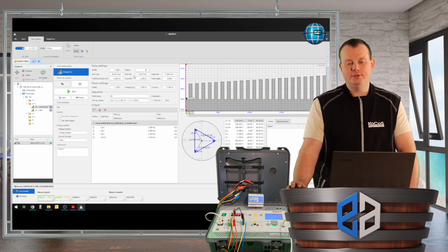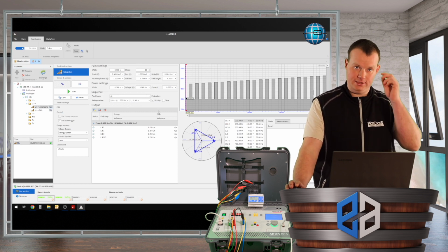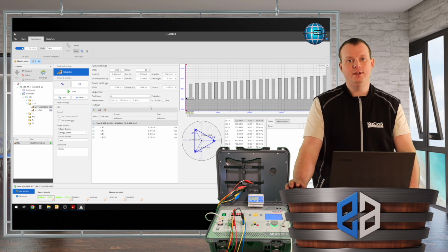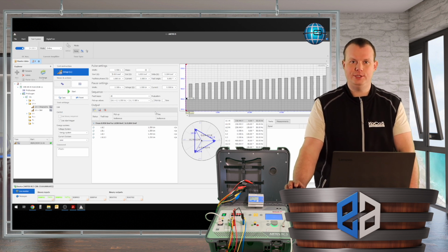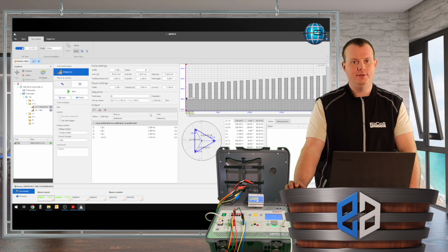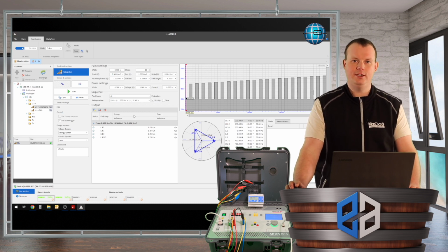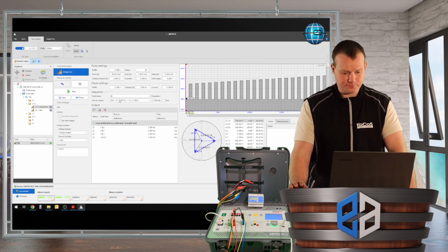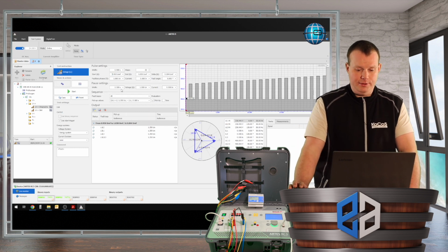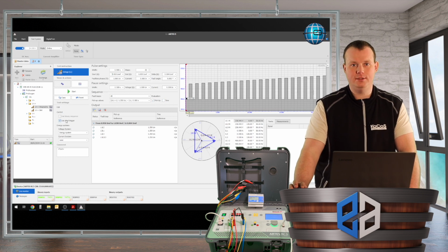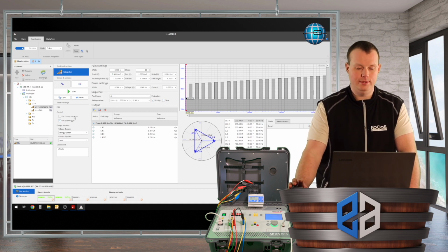This enables us to use this test job later on for different relays, and in case there is another threshold, we only have to change this one in the IED settings and the ramp is recalculated automatically. I did this for all the fault loops, and with this ramp I only would like to evaluate the pickup, not the time. Additionally, I use the start trigger to wait for the reset of the relay.